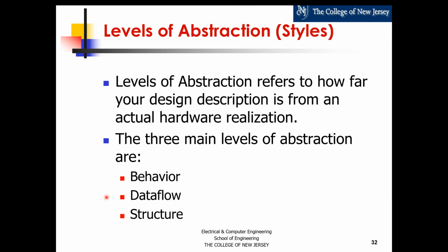Now, even though I don't have it here explicitly, there is a level right between behavior and data flow. It's higher than data flow, but not completely open-ended where just the behavior is captured. You're capturing a little bit of data flow as well with some behavior. So somewhere in the middle. It's higher than data flow, lower than behavior. We call that synthesizable. That's what you're going to have to be writing. It has to synthesize.